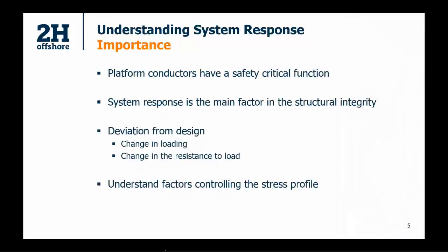So why is it so important that we understand the system response of the conductor? It's because the platform conductor is pretty critical when it comes to the whole platform system. And most of the time it is the structural member that's supporting the well, so any potential issues with that then has consequential results inside the well, like downhole. I also talk about the system response. So the response of the system is the main factor in the structural integrity.